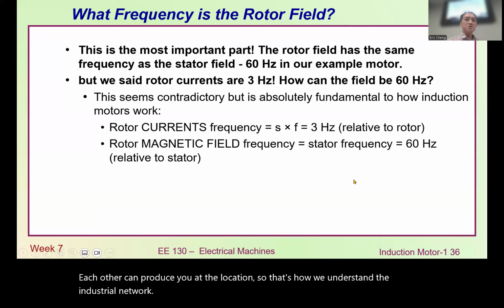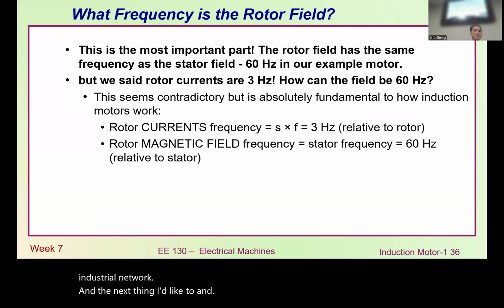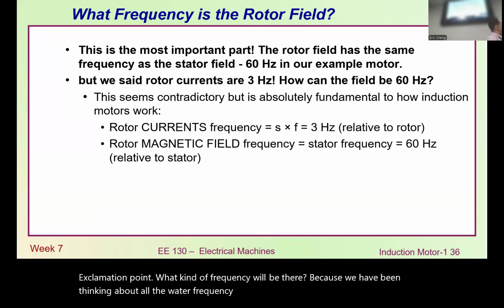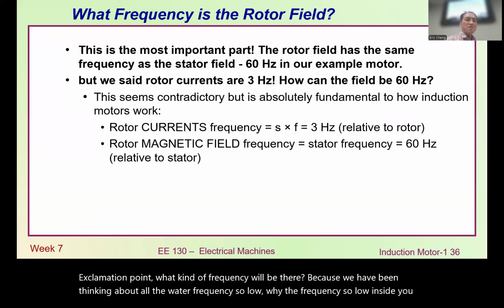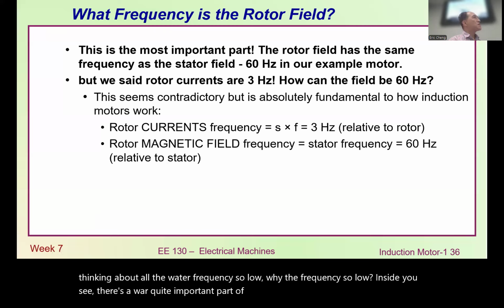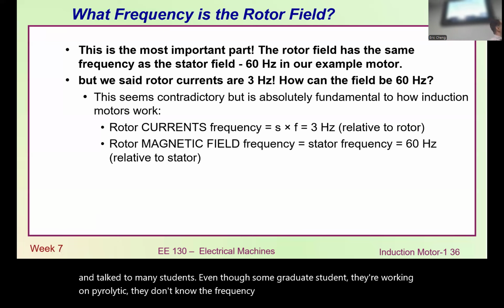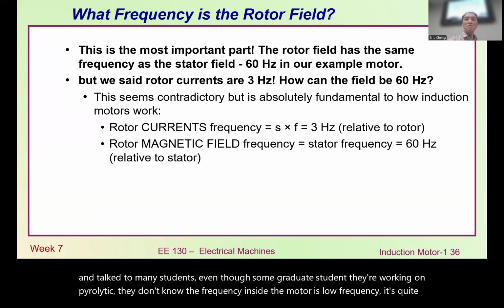And the next thing I would like to examine is what kind of frequency will be there. Because we have been thinking, oh, the rotor frequency is so low. Why is the frequency so low inside? You see, that's a quite important part of the induction motor. I have taught many students, even some graduate students working on power electronics, and they don't know the frequency inside the rotor is low frequency. It's quite surprising. So let me explain what happens.